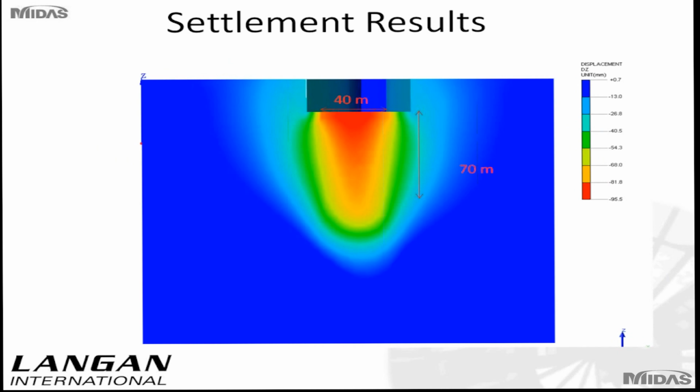Now this is a cross-section with soil settlements, again one of the benefits of working with finite elements. This distribution is typical of a pile-raft foundation where the soil settlements are relatively high at great depths because a bigger soil mass is engaged compared to just having a raft without piles.